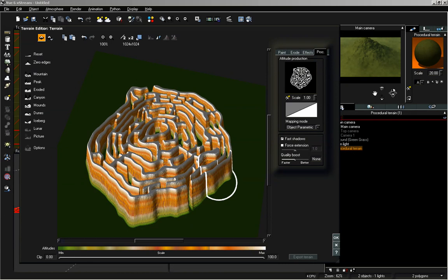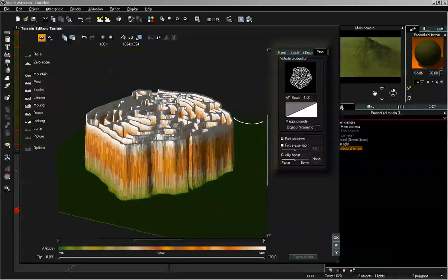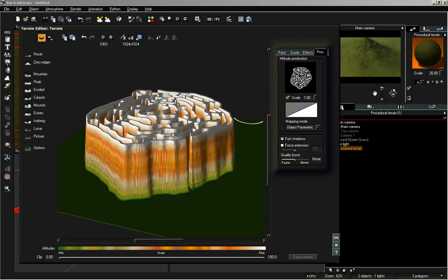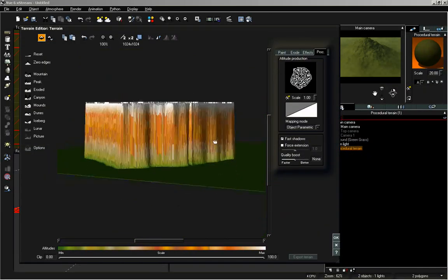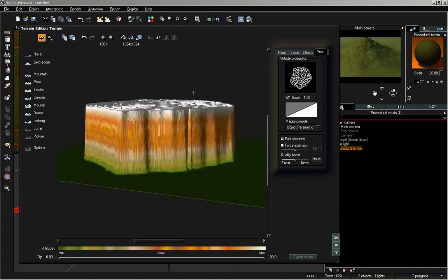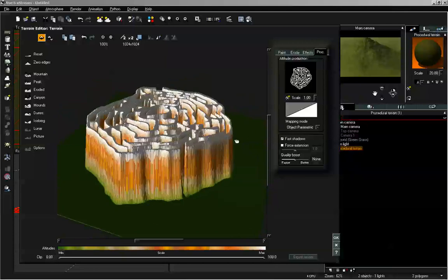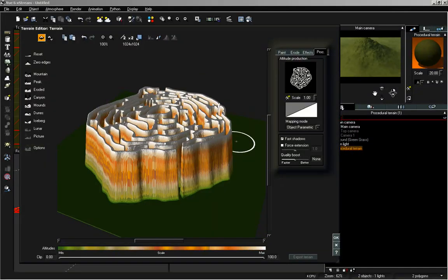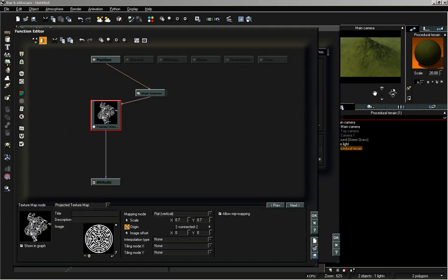Now, because our image map is white on the areas that are sticking out, we're not seeing at this point the way this turbulence node will affect the vertical of our hedge. So what I will need to do in order to actually see how the turbulence node is affecting it up and down, which will show up when we render, but just not currently in our preview, I would just need to make a little modification to our image map.